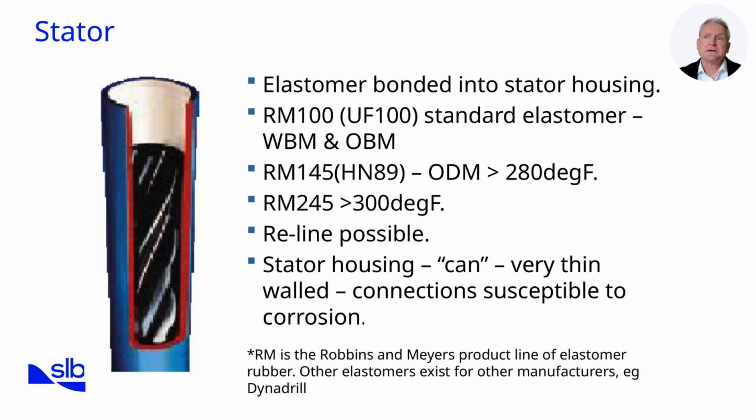Stator housings are relatively thin-walled, making them susceptible to corrosion, especially at threaded connections. Manufacturers have also developed contoured stators, which provide more even elastomer thickness compared to traditional designs, improving durability. Understanding stator limitations and choices helps drilling engineers minimize motor failures and extend downhole performance in challenging wells.